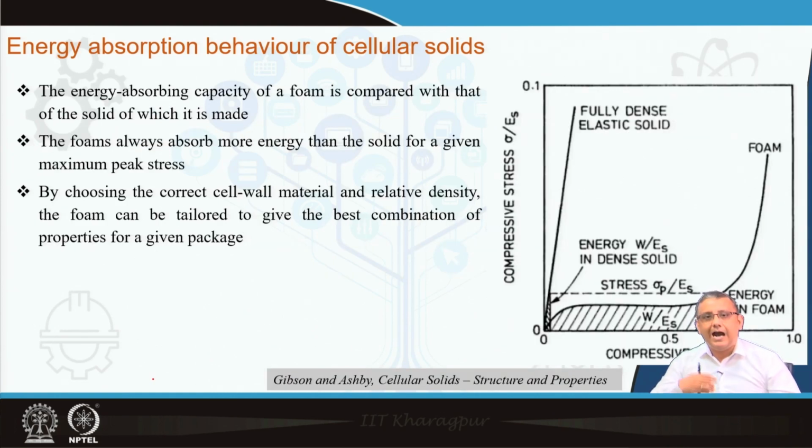Now, the question is, how do foams actually provide the energy absorption behavior? We discussed this briefly in one of the previous lectures, and in today's lecture we will discuss it in much more detail. As you can see, a typical stress-strain plot is being shown here, and this is under compression, because I mentioned several times that the main applications of these foams or cellular solids are under compression. As these materials have a significant amount of pores inside, if we put the material under tension, the pores will act as stress raisers, and the material will fail or crack very easily.